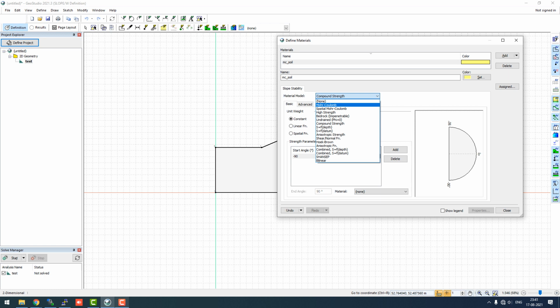But I'll let you know that 90% of the time you will use Mohr-Coulomb for the soil material, and you will use Hoek-Brown parameters, which can also be simplified into Mohr-Coulomb. If you have seen any software like RocData, there are curves which can directly simplify Mohr-Coulomb parameters from Hoek-Brown parameters, and vice versa. So you will be using, mostly 90%, or let me say 99% of the time, Mohr-Coulomb plus Hoek-Brown. These two failure mechanisms or plastic parameters will be good enough to know.